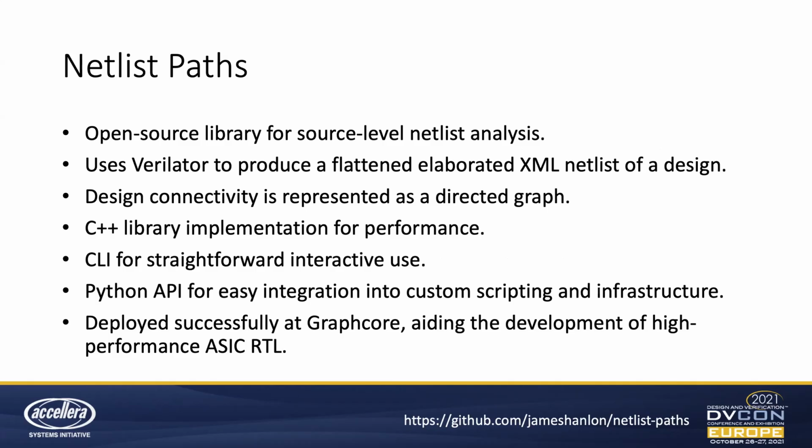In order to get Verilator to do that, we did make some changes to the Verilator source code, in particular to get it to flatten the design. So this is where it inlines all the modules, and you end up with a single module with all of the design instanced in it. Then it takes the XML, it reads it, it works out where variables are, it works out where the data dependencies are between the variables, and it creates a directed graph as its main internal data structure.